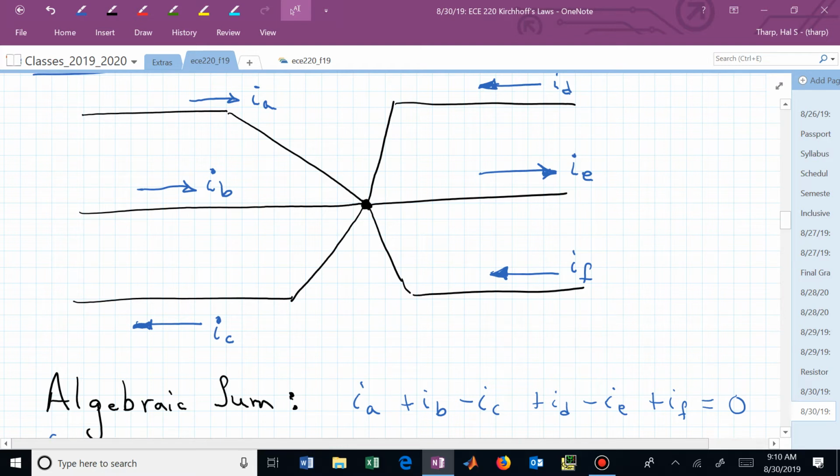Obviously, we would have to express those. Right now, how many do we have? We have 6 variables. If we just had those 6 variables, we would need more equations in order to solve for those. And that's what we're trying to do in this class, is figure out, if I have this relationship, how do I use that to analyze the circuit? So we'll have to combine some of these different strategies that we have in our toolbox of techniques that we'll apply this semester. And this is one of them, KCL.